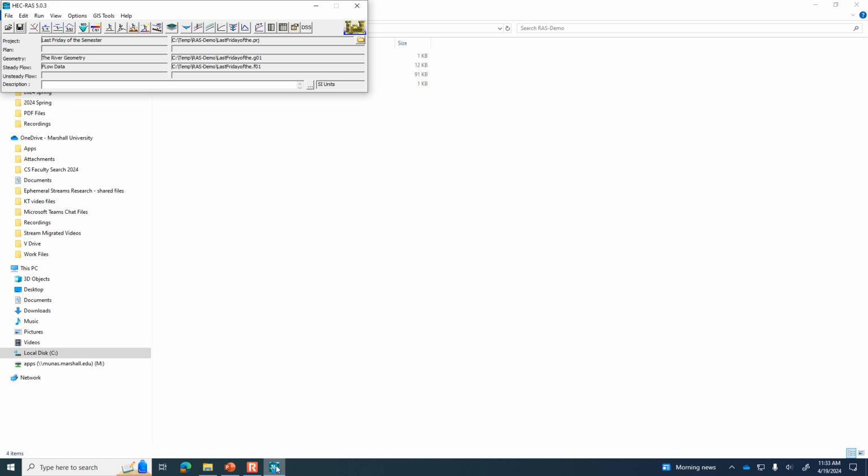So now we have to tell it to do the calculations. So we've got a channel, we've got a flow rate, and a location where the depth is known. So now we're going to do a steady state run. So here on these little buttons across the top, it's this one. It's a person running on a flat ground. So that's your visual reminder. We're going to do a steady state flow simulation, just with that known 15 cubic meters per second. So click on that.